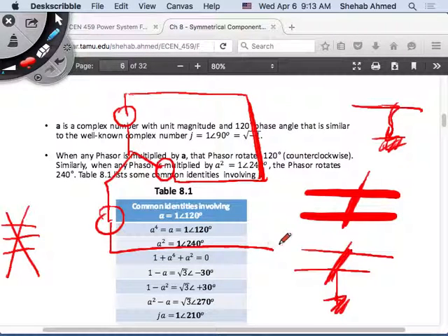Let's say not connected. What will happen? What does Kirchhoff's current law tell us about the relationship between these two currents? Yeah, they're equal and opposite. These currents will be equal and opposite. And if I have no current flowing here, then I don't have any current flowing in the neutral. This is 0, and this one is equal to this one. The current here is 0, for example. It's not connected. There's no connection here. And this current is equal to this current and opposite in magnitude. So what is the current flowing here?